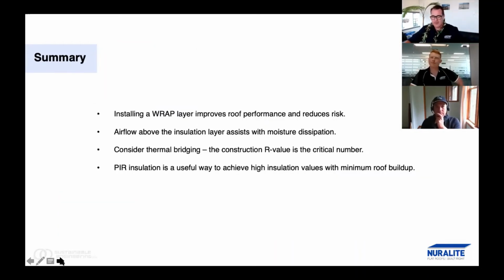All right, so just to quickly summarize what we try to cover today. So we're saying that installing a wrap layer is very important. So that's your water, air, vapor control layer. No matter what you're doing, that's probably the key takeaway there. It's going to improve your roof performance and reduce your risk. It's going to give you that sort of level of redundancy that you may need because conditions change and building uses change and things like that.